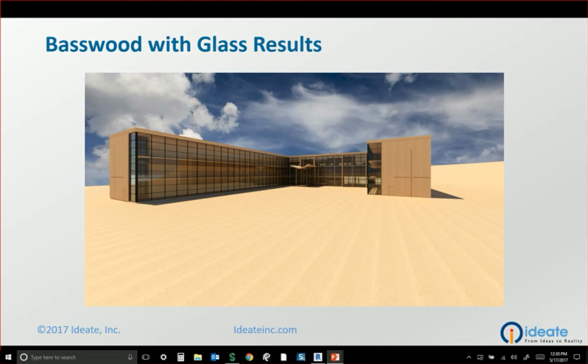Yeah, absolutely. So the question was, can you elaborate on moving the glazing to the future phase? I should be careful with my terminology by saying future phase. What you want to do is come in and add a phase at the very end of all your phases and just call it like glazing. And then what you have to do is you want to select anything that has a window. Now, it can get a little tricky because, like, what do you do with a door that has glazing in it, right? Because that's a family. Because the door will become that whole component that you have to move to the glazing phase. So there could be a little bit of trickiness over there.